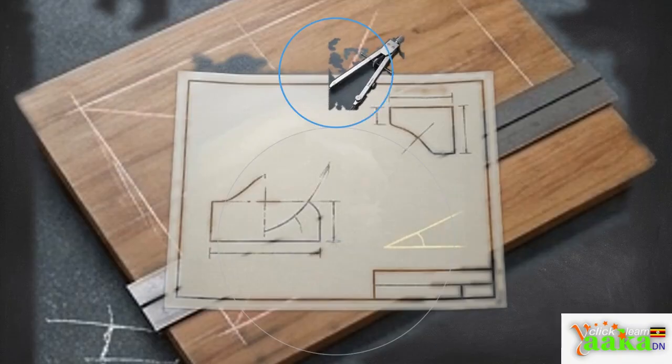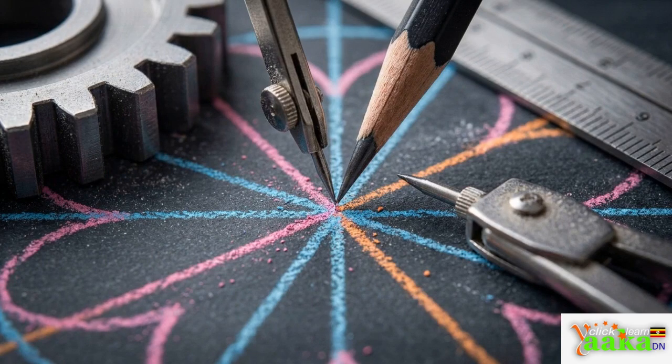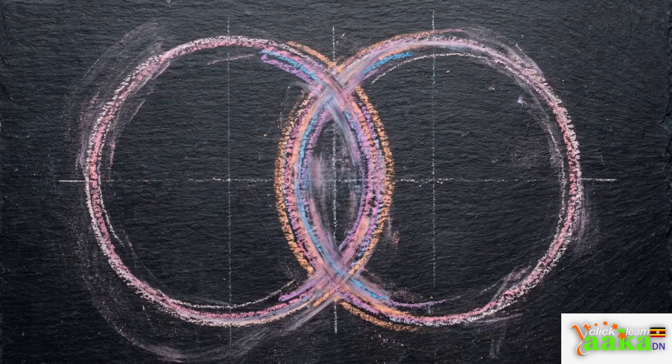In this diagram, you can see how the smaller generating circle rests perfectly on top of the base circle, touching at exactly one tangent contact point, labeled P. Establishing a perfect single-point tangent at P is the physical foundation for the rest of your drawing. Any overlap or gap here will distort the entire mechanism's movement.